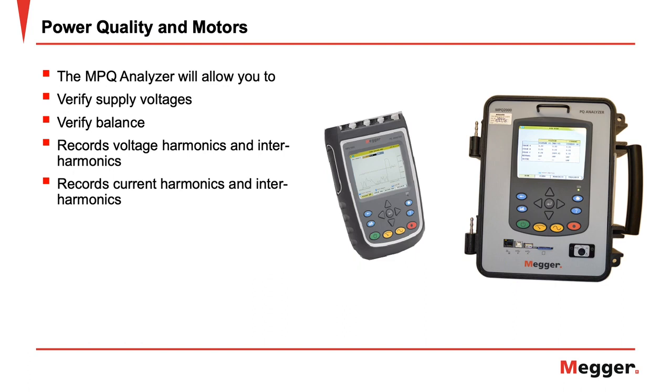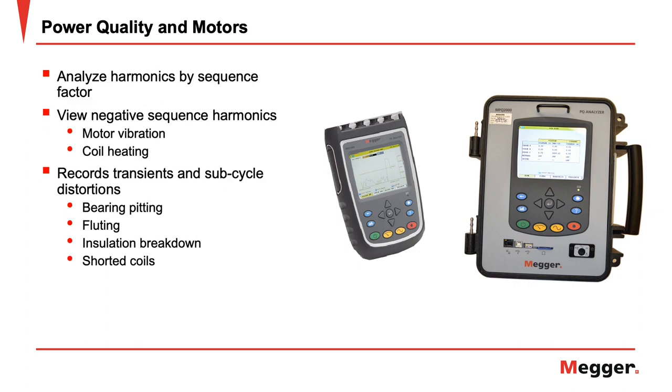High levels of current harmonics as well as high frequencies cause elevated heating in motors that can lead to a host of failures. The MPQ analyzer will analyze harmonics by sequence factor. This allows you to view the negative sequence harmonics that can lead to motor vibrations and additional coil heating.